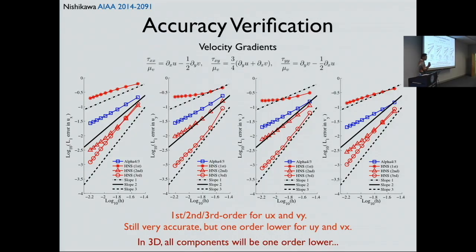So I was able to get the second derivative of the velocity to one of lower accuracy, because these are gradients. And by using these second derivatives, I can do quadratic least squares on a linear least squares tensor, because the curvature term is given. That's how I got these 2 results, uy and vx.